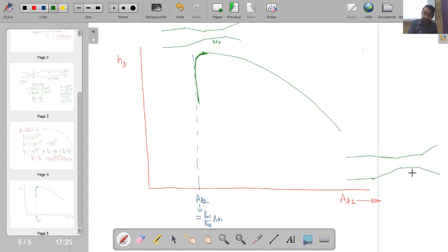If I increase the throat area, here the flow will be supersonic. And due to the supersonic nature of the flow, I will find that in the diffuser section there will be occurrence of a strong normal shock wave. So as I am having a strong normal shock wave, that leads to a significant drop of pressure over here. So that is the reason that if I keep on increasing the area, my efficiency will keep on decreasing. Okay.